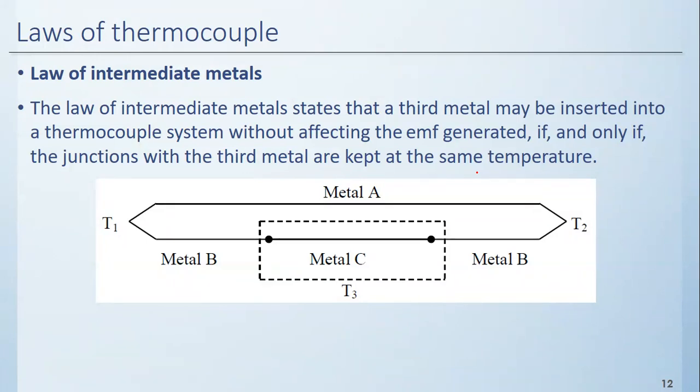Okay, in such cases, you may think this material addition or instrument addition in a thermocouple will affect the EMF produced. But it is wrong. The EMF produced will be the same if the two ends of the metal are at the same temperature.